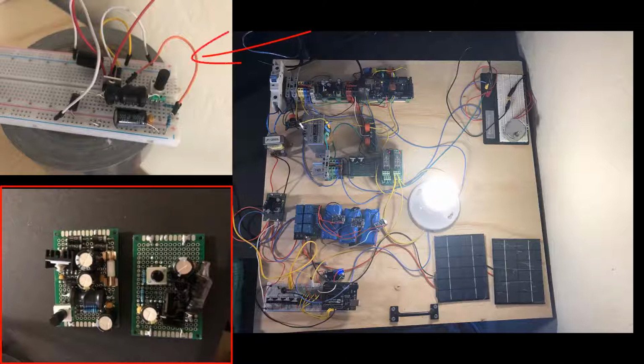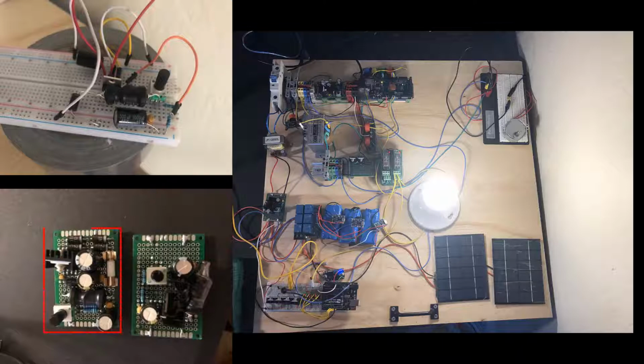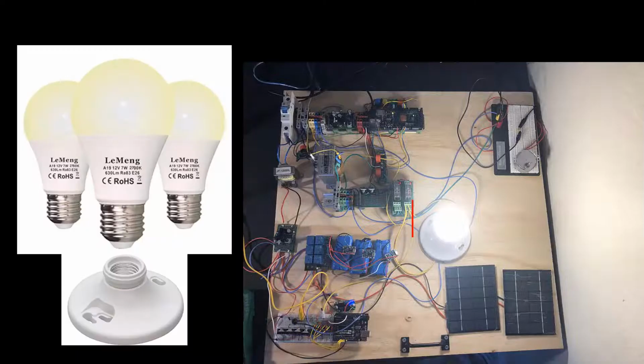This is the first prototype that was tested on a breadboard and then soldered later. Here is the second prototype that implemented a rectifier circuit on the PCB, higher end capacitors, and an inline fuse. Our residential load is essentially a resistive 12-volt AC rated light bulb. This bulb will get powered from either the inverter during an outage or the utility transformer during normal operation.